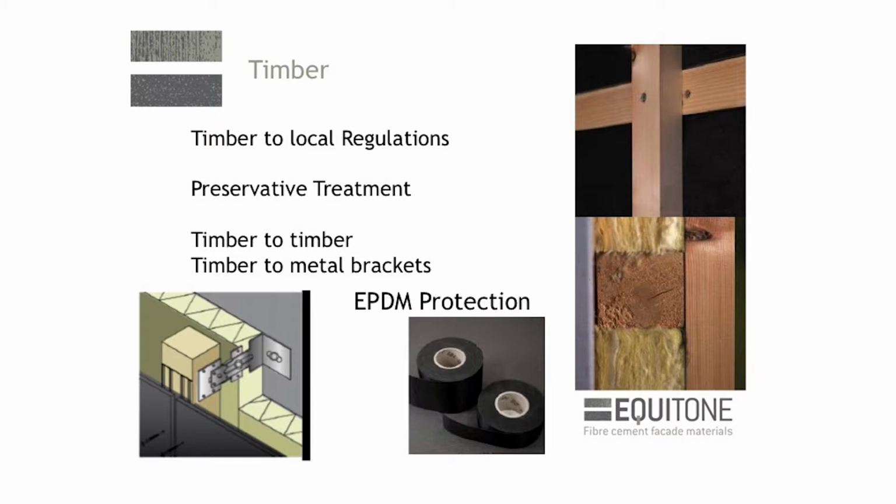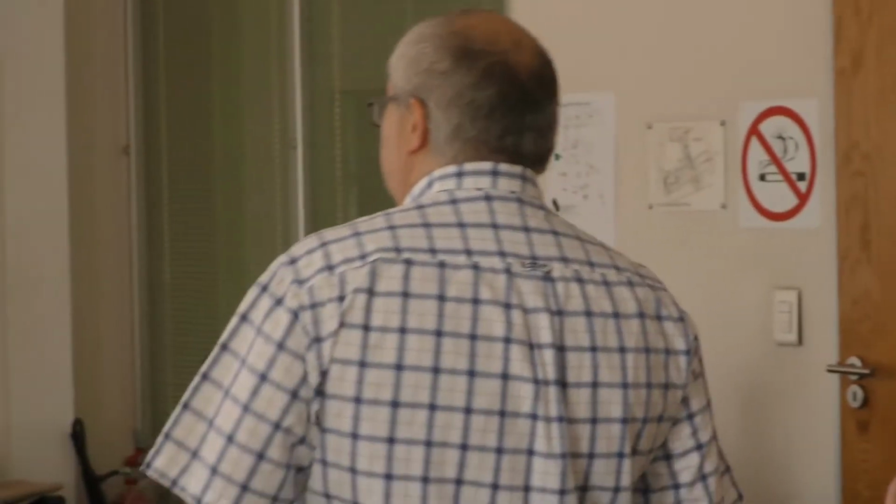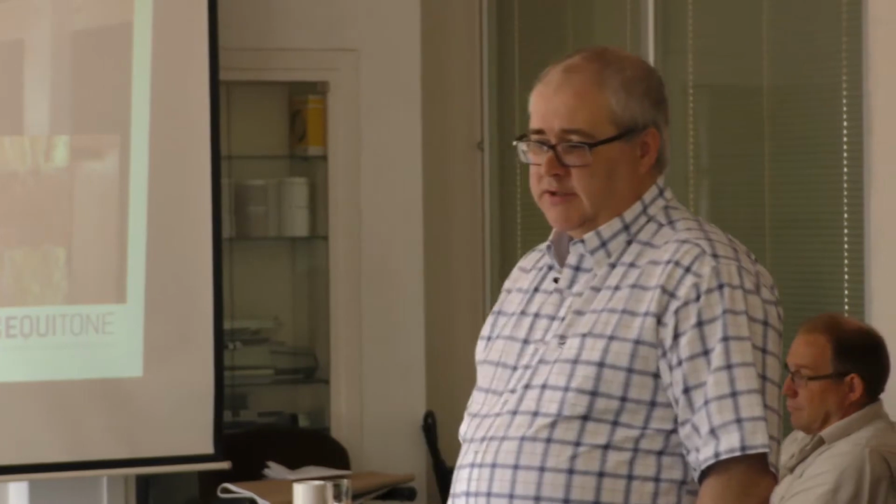I would say probably it may not be the most commonly used thing, but I still think you may end up having to screw fix onto timber battens. We have everything to do it, we have all the accessories, no problem, no issue. However, the only thing that you have to be careful of is preservative treatment here. I believe you do have termites, longhorn beetles maybe. So the type of timber and the preservative treatment is very important.